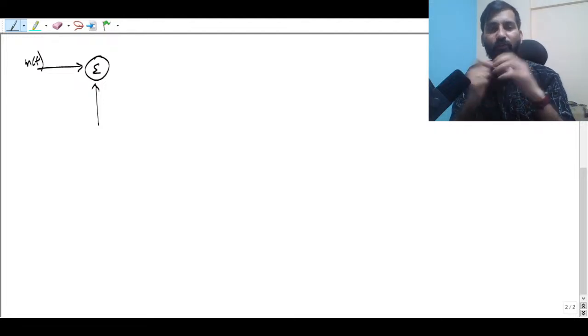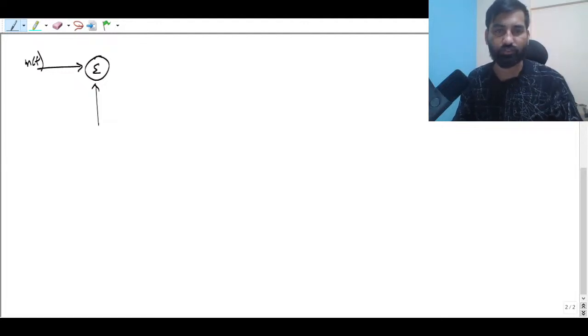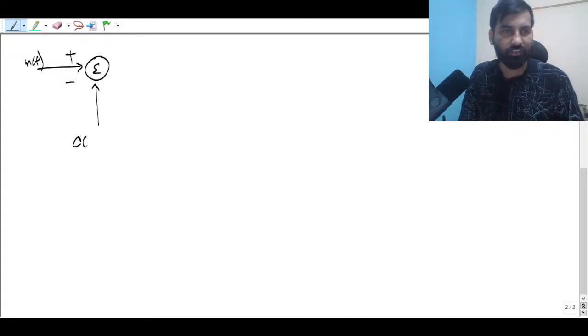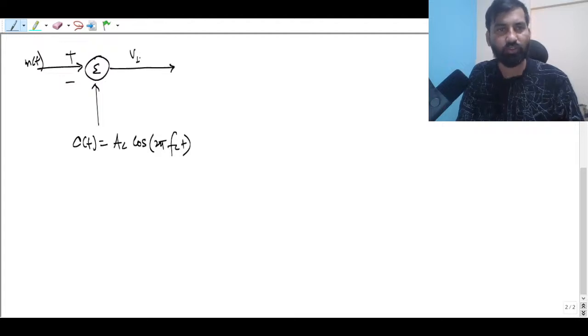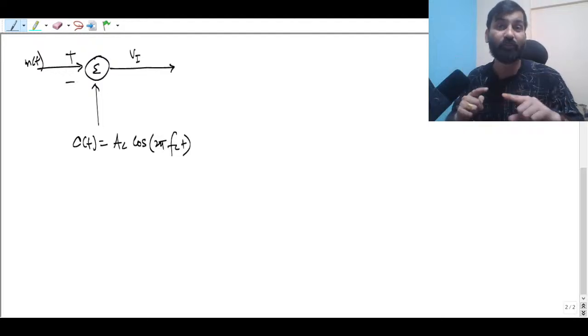So first of all, you take the message signal and put a summer here. You will add your message signal with a carrier signal, and the carrier is Ac cos 2 pi fc t. Then it will produce some output that is nothing but vi. So I'm talking about the modulator, guys. Where does the modulator exist?